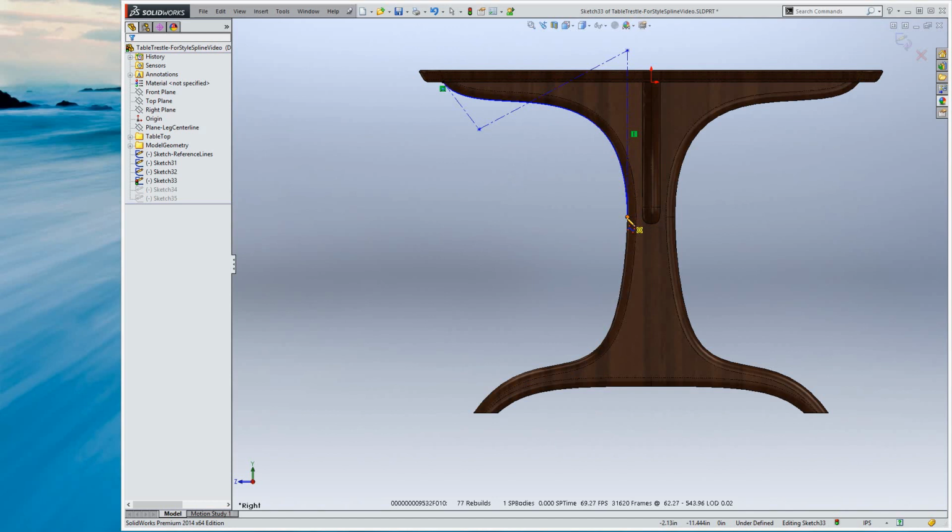Obviously we get a very nice curve when we do one style spline for the top half, so I'm not going to try and do this all in one spline. That way I can constrain to this point here because we want it to meet here. I find that in general with style splines, if you have constraints, you should only add those to the end points of the style spline. You can constrain the spline itself to points, but with style splines it's better to avoid that. So let's go ahead and make this two separate style splines.